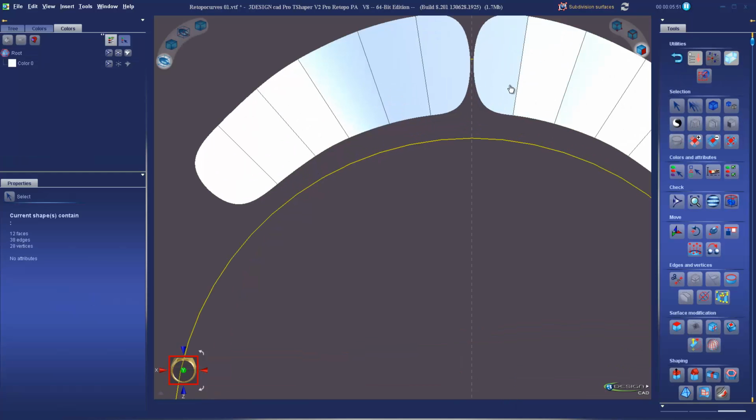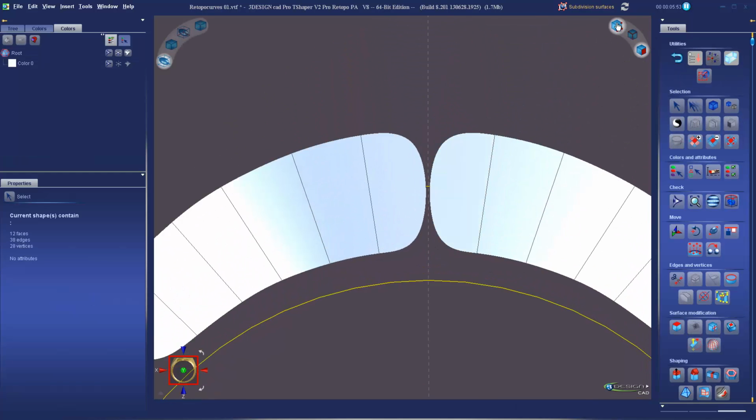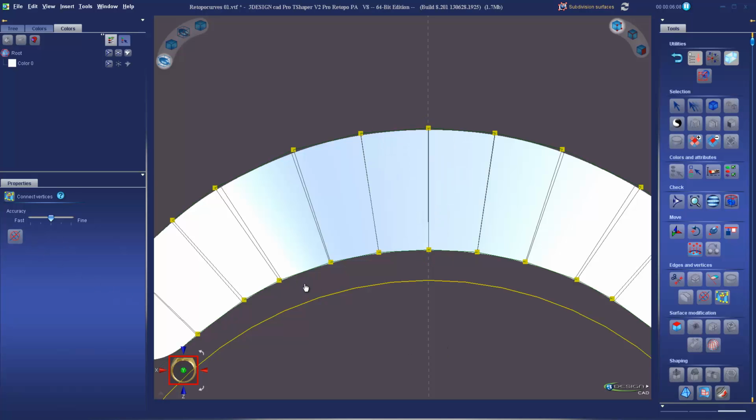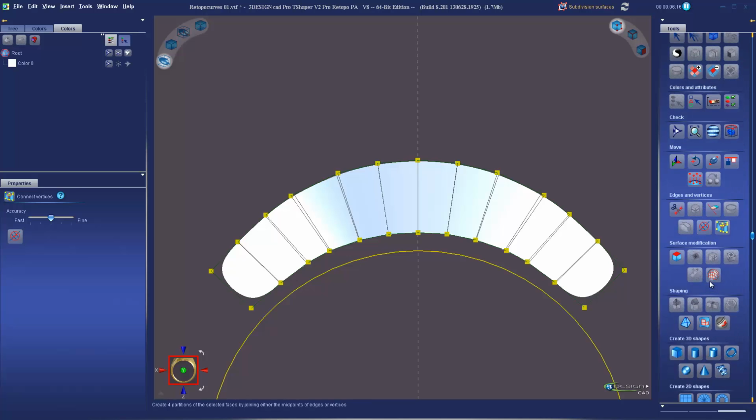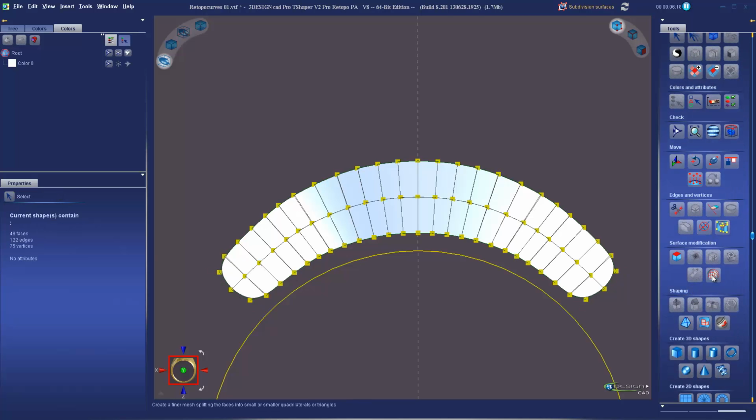Back in our tools, we'll add a new edit surface to it. And we see that these points here aren't quite connected, so we have this gap. We'll use our Connect Vertices tool. That'll highlight any of those superposed points and just click the button to automatically join them. So there's our shape. We go ahead and subdivide this. I'm just going to do a quick refine on it.